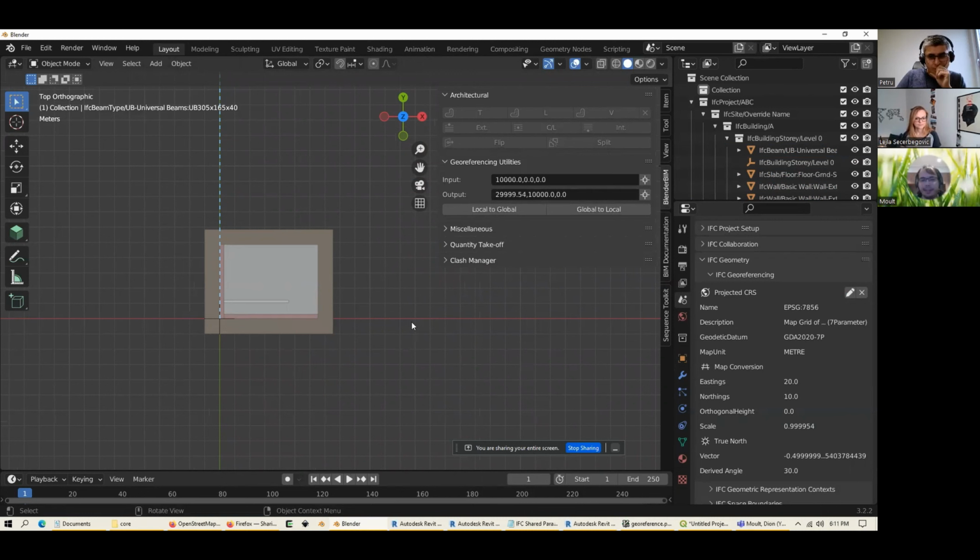And that's nothing. You know, if you have a small project, you can absorb these inaccuracies in your georeferencing easily. The problem comes when you have a larger project. So for example, you've got a 200 meter long project, you're going to start getting a much bigger deviation or inaccuracy. You could get 2 centimeters off, for example, or 15 mil off. And it also therefore means that you should be very wise in choosing where your false origin is.